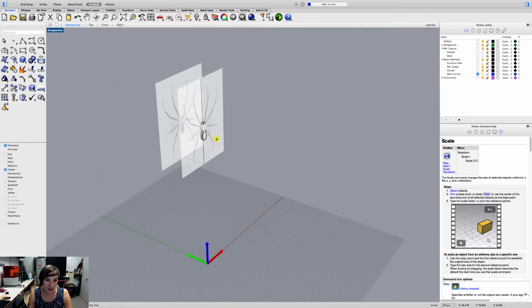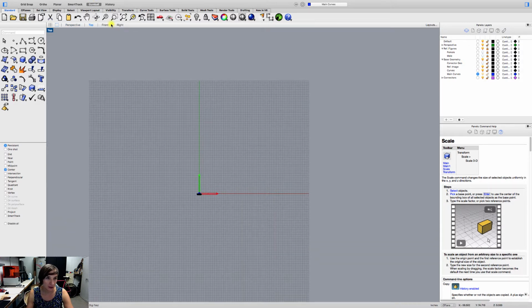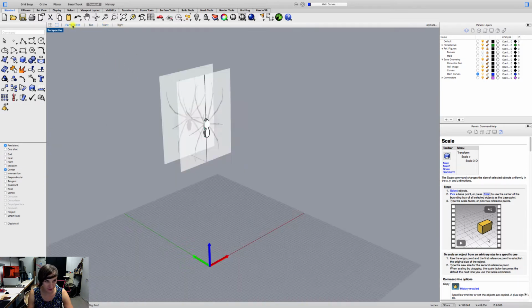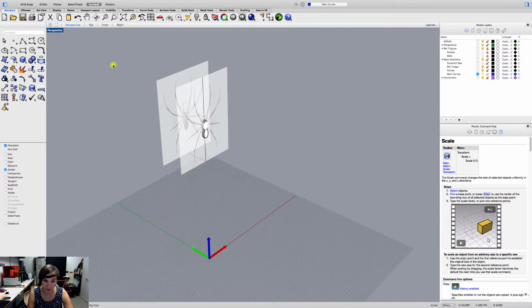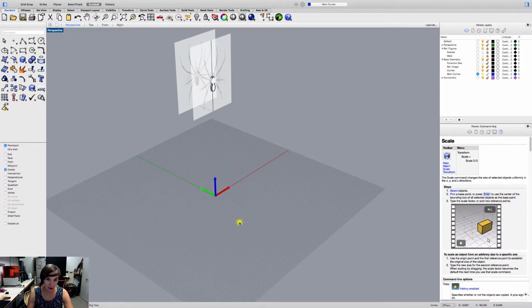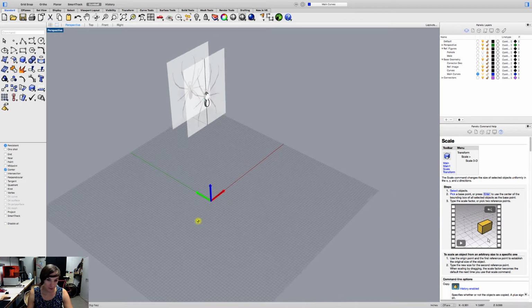So some things to note in this file is this is the same sort of perspective reference that I made in one of the first lectures. And that spot represents the world coordinate system. So right now, when you start a file, all of your planes and views are aligned with the world coordinate system. And that world coordinate system doesn't ever change, but you can move the coordinate plane around this plane right here to wherever you would like it. And when you do that, it's going to ask for different features.